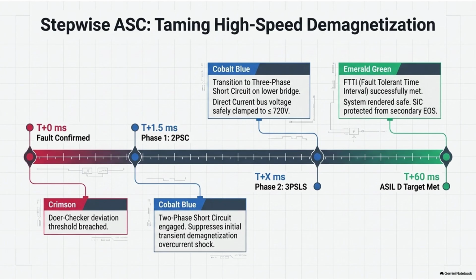However, at the high frequencies generated by silicon carbide switching, a pigtail has significant parasitic inductance. At 10 kilovolts per microsecond switching speeds, the impedance of that tiny pigtail wire becomes incredibly high. The shield is no longer effectively grounded at those frequencies. Instead of shunting the common mode noise to ground, the pigtail actually acts as an antenna, radiating the noise right into the sensitive inner wires. By mandating a 360-degree clamping connection with a grounding resistance of less than 10 milliohms, the design maintains a continuous low-impedance Faraday cage around the signal wires. Completely blocking the capacitive coupling of the noise.